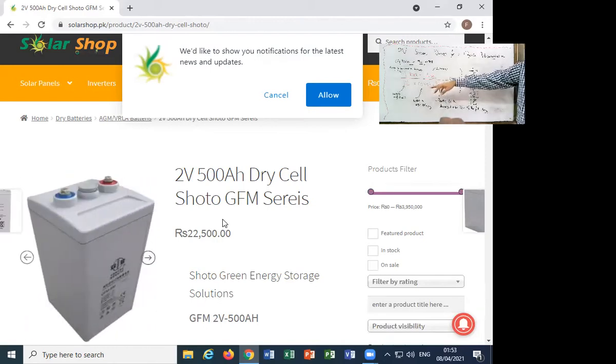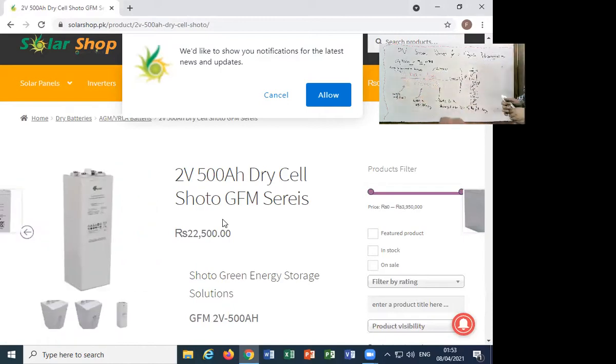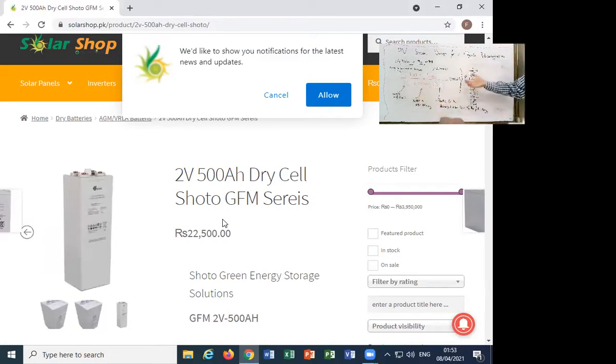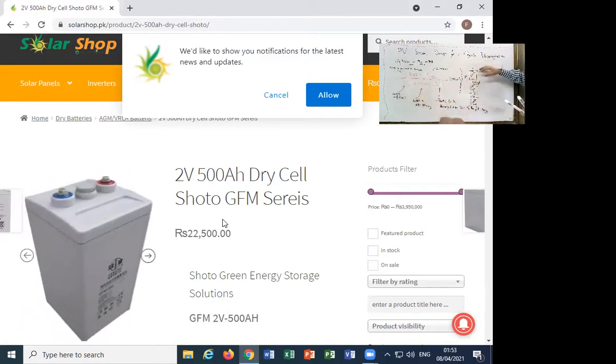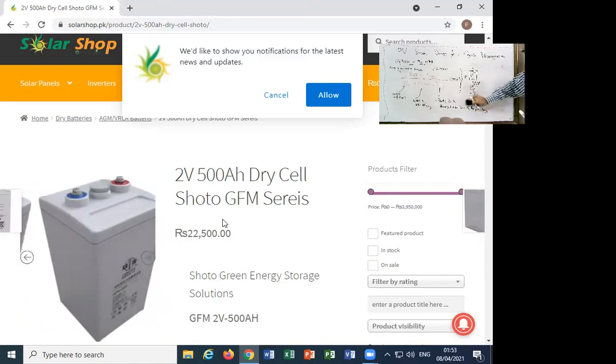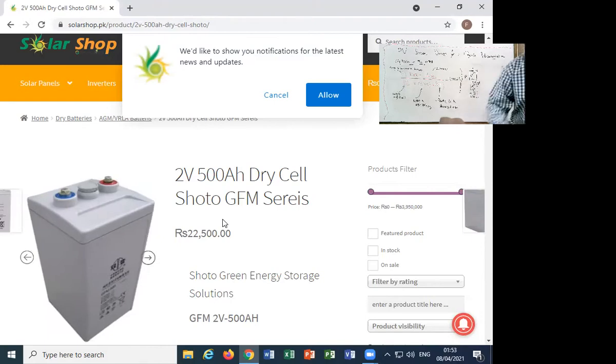Whatever the battery voltage, we started from 12. Now, this is just an indication that you need a 9000 ampere hour battery. It is not necessary that you make this a 12 volt battery bank. We can make it like, let's say we connect these 6 batteries in series: 1, 2, 3, 4. Let me connect them.